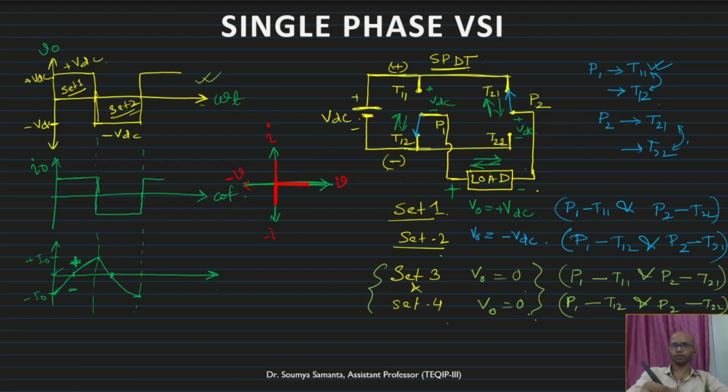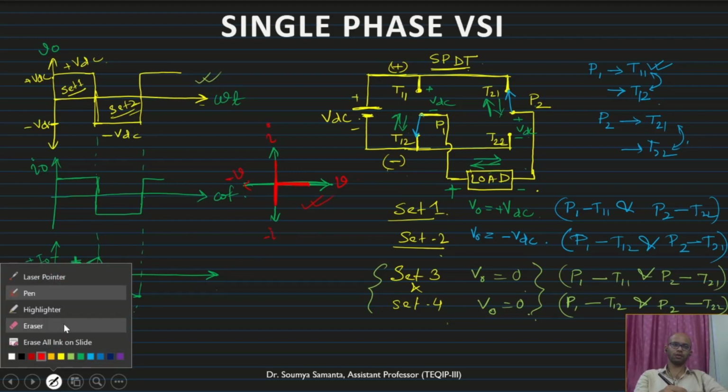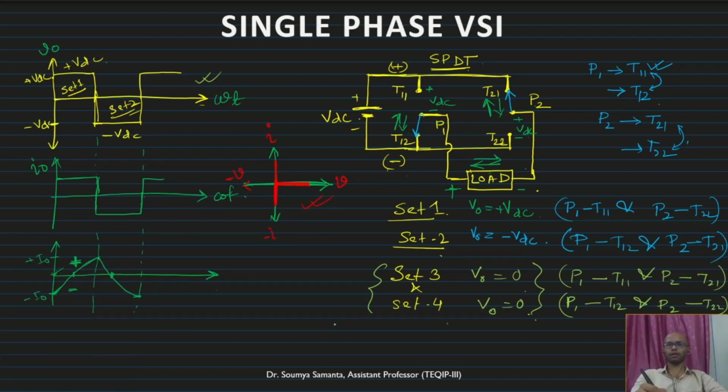The switch. Okay. So bidirectional current conduction capability and unidirectional voltage blocking capability. These are the characteristics the power electronic switch has to have. Now let us check what the power electronic switch pattern will be.